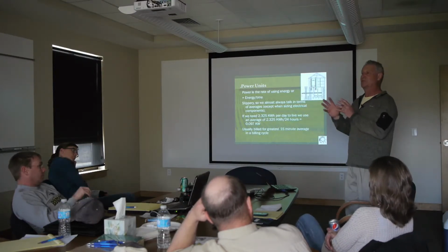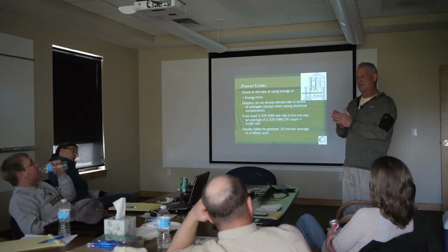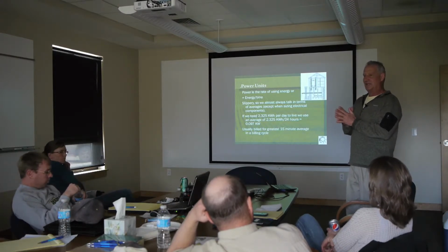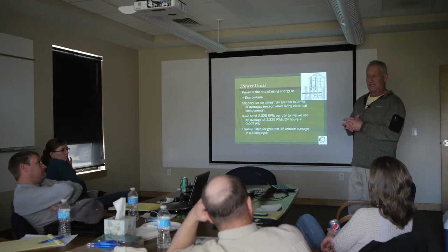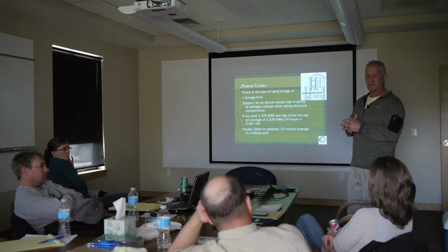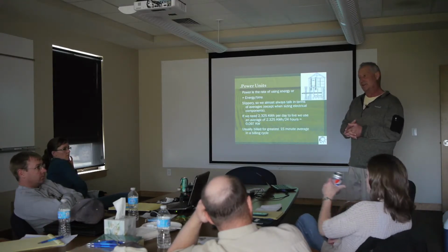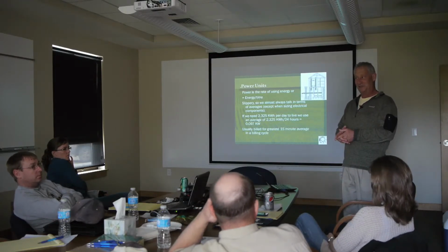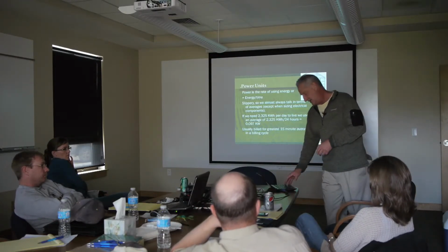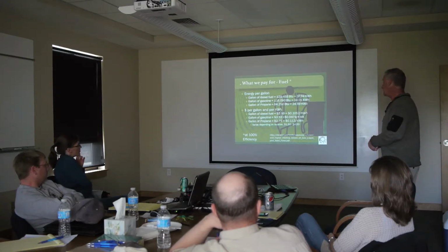This is very important, because it's just 15 minutes that sets that peak. If you have some machine that demands 100 kilowatts and you only run it 15 minutes in the month, the demand charge is the same as if you used that machine all the time. You can mull that over, because we'll talk about it some more later.